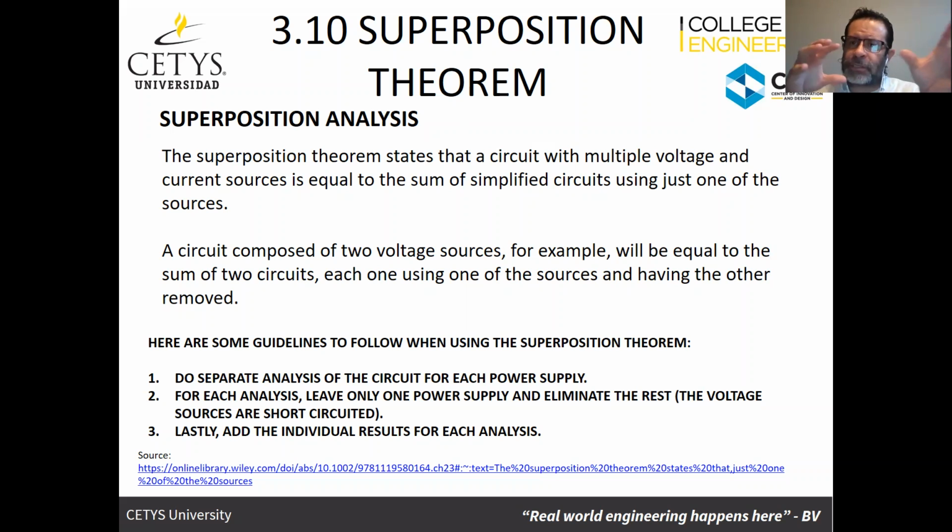And when we talk about a linear system, remember that linear systems have a mathematical definition. They are systems that can be represented mathematically in a certain way and have certain properties. One of their properties is the superposition theorem. The superposition theorem says that if I have a system that has many inputs or stimuli, the total effect or result of those combined stimuli is equal to the sum of the individual effects, or the individual contributions. This only happens for a linear system.